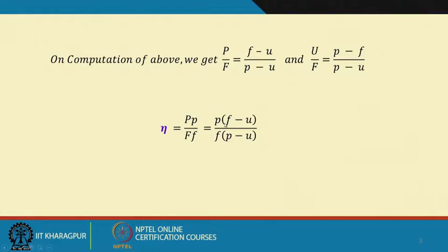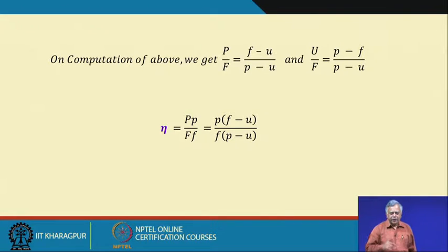Now, I have recovered in the oversized material a total of 40 tons. So, that is nothing but your capital P, and out of that 40 tons, we have seen that we have got 90% of the material, or the 0.9 fraction of that is plus 5 millimeter. So, how much have we got? We have got 36 tons of that plus 5 material.